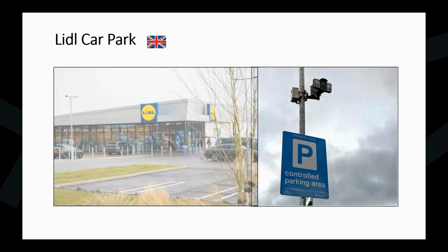The tricky thing for this one, though, is that for Lidl's in particular, they wanted to install the cameras and the lighting on existing columns in the car park, rather than installing a specific ANPR column in order to do that. Now, what this meant is that the camera and lighting was at quite extreme angles to the vehicles actually approaching or entering the car park. And we'll look at this a little bit later, but some of them were essentially outside of the 30-degree retroreflectivity zone of a European plate.